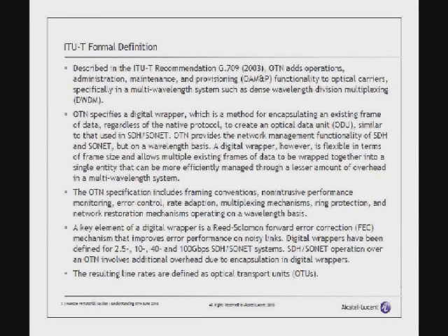As with any standard, OTN specifies framing conventions and methods of doing performance monitoring so that the operators can get a sense of what is going on with their optical network at the DWDM layer and provide information that wasn't there previously. Prior to OTN being available, basically all you were looking at is transmit power and bit error rate.